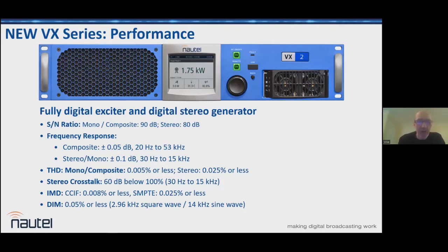The RF amplifier technology is cutting edge. It's using the latest LDMOS FET. It's the FET that a lot of transmitter manufacturers use today for FM broadcast, which has similar specs regardless of which manufacturer you go to, and most of the big players are using the same device. This is the next one, more evolved, with better performance, higher drain breakdown voltage, and less susceptibility to a phenomenon called snapback, if you're familiar with how FETs avalanche and fail.